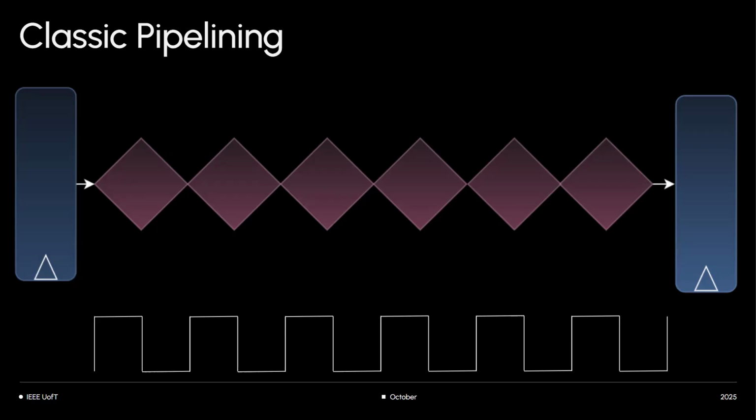So in all this so-called idle time, when these flip-flops move things at the positive edge, yes, there is a hold time. If you have heard of setup time and hold time, it's just a timing parameter, so don't worry, you're not missing out on a lot. Everything else before the next positive edge is just idle time, sitting idly, not doing any work. You can see that with Robert: he finished fast, and he was dying to move forward, but the clock didn't allow him.